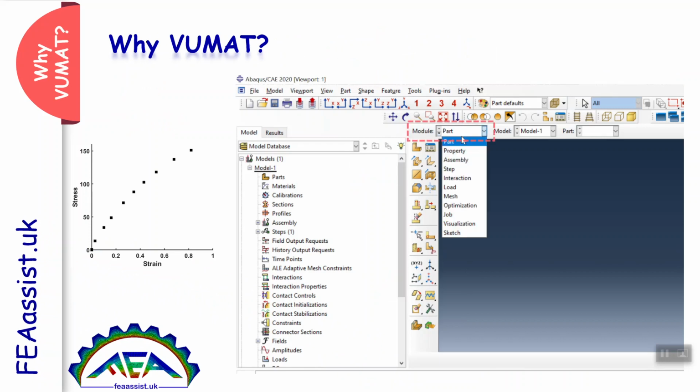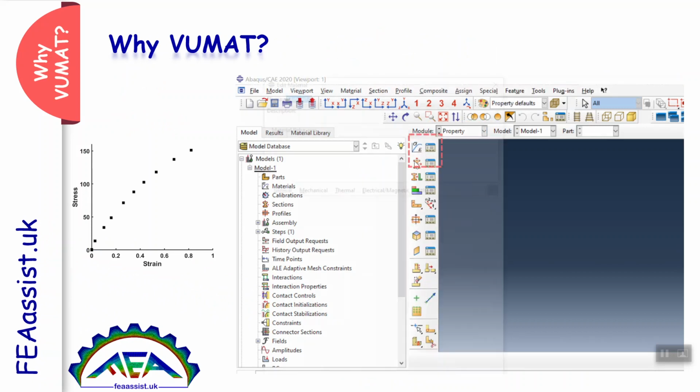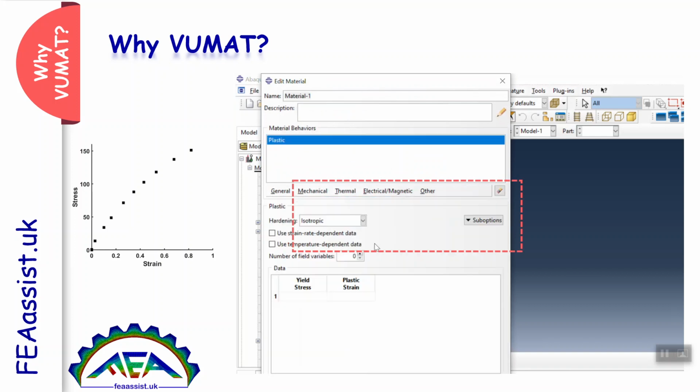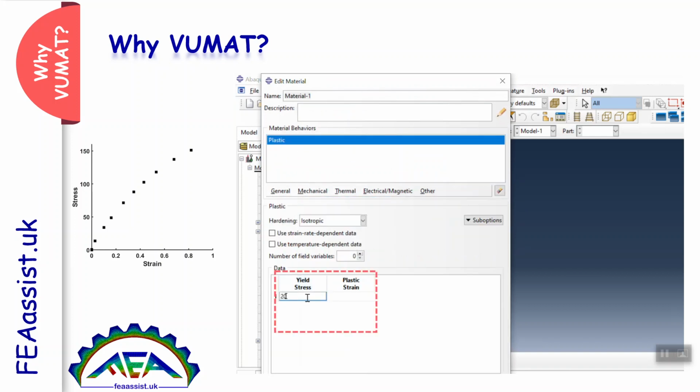Then you can easily go to the Abaqus property, define a new material, go to the plastic behavior and enter those points like this. Abaqus interpolates between these points and predicts the behavior of the material in all points. This is the simplest way, but it is not precise because of interpolation.